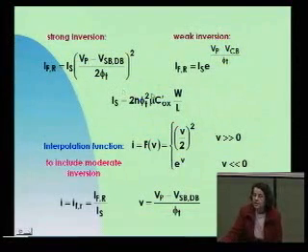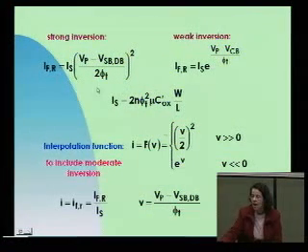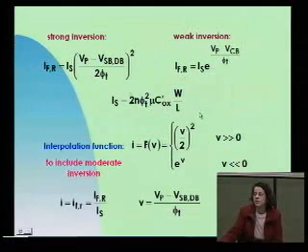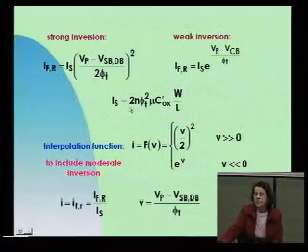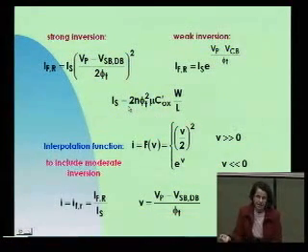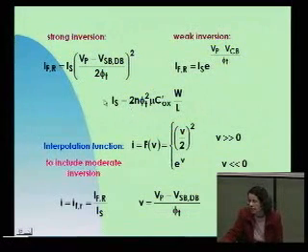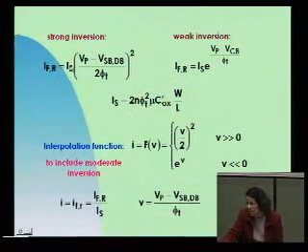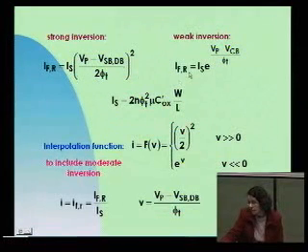This current is the most important parameter of the MOSFET for circuit design because it has all this information, geometrical and technological, inside it. Then with IS and VT, you can do almost everything in hand calculations. Okay? Then you can notice that this current appears in both asymptotical approaches.